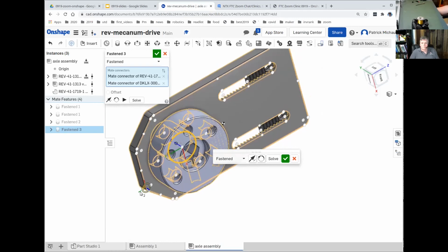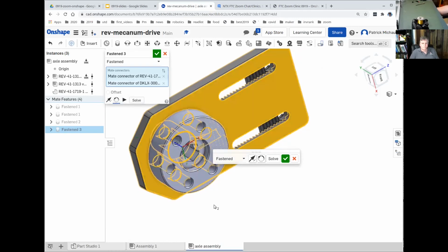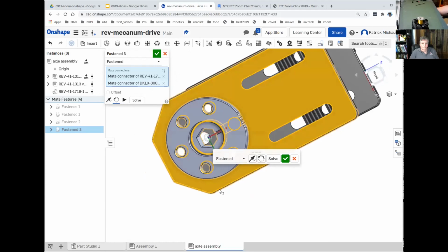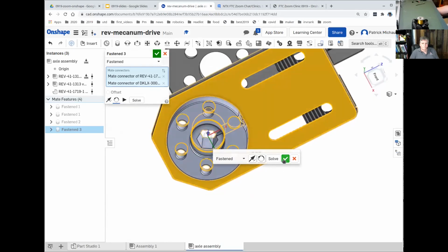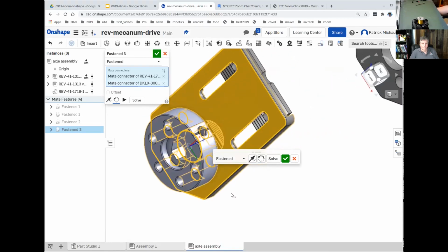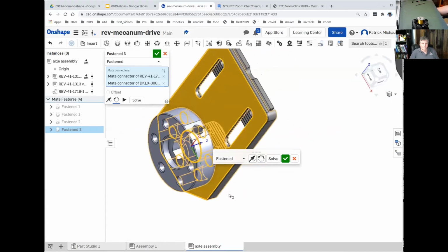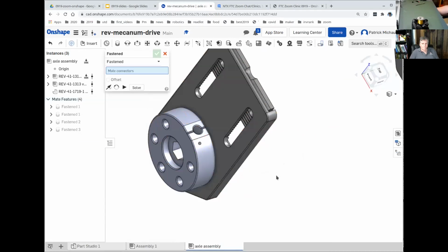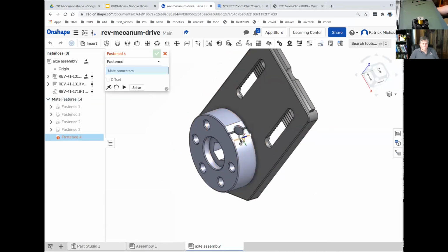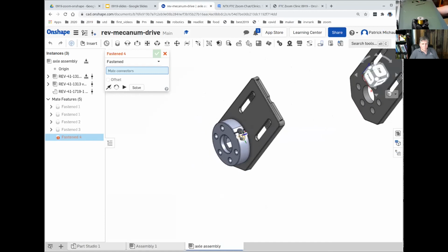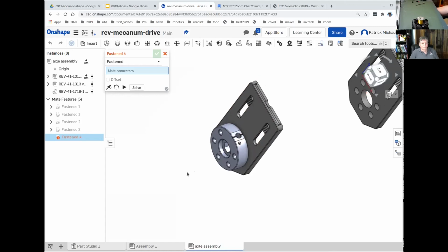And I'm going to turn it 90 degrees. And hopefully, maybe, yes, the hole's lined up for me. So I'm just going to leave it at that. Actually, that's a potentially bad 90 degrees, because what that does is it puts the set screw hole on the top. And later when I've put this onto my chassis, that hole may be hard to reach because there may be things above it. It would be much better if the set screw hole was facing a different direction.